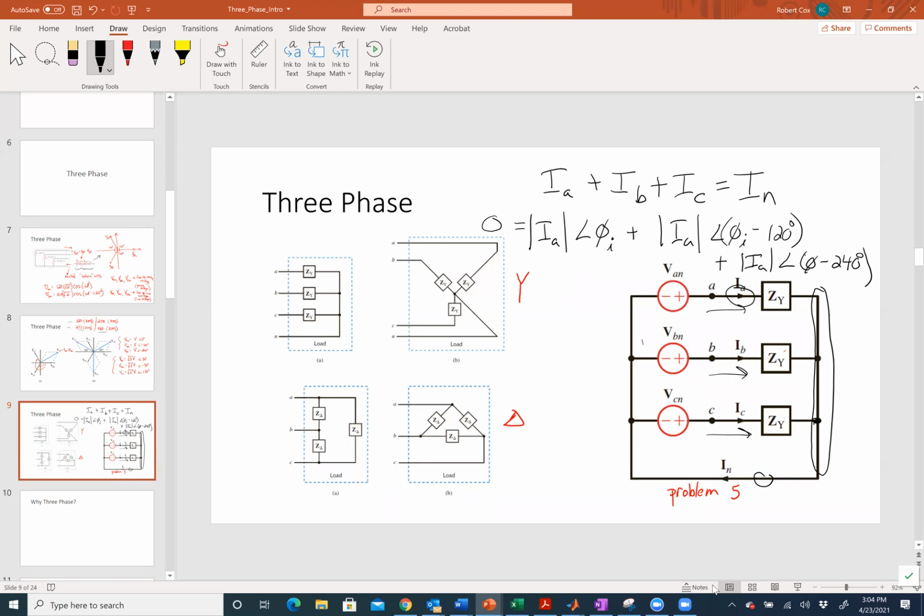IN is 0, right? So I could have a really small wire, right? So effectively, and if you think about it, copper is an expensive resource, right? So effectively what this means is, if I do 3-phase like this with 120 degree separation in the voltages, I can basically have these 3 circuits running with half the amount of wire it would have taken for one. All right, it's sort of the idea, right? So that was really kind of what drove it initially.